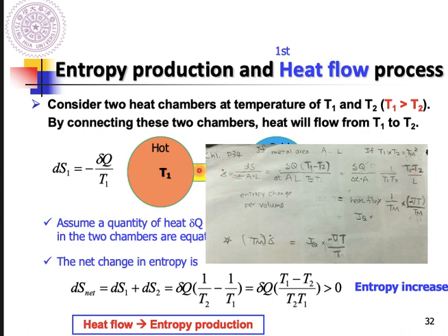Usually, in most cases, the flux goes from here to here. So for the gradient term, we usually use the end point minus the start point. So it will be T2 minus T1 divided by L that is the gradient term. So here I get the minus temperature gradient. Okay, so now we have the flux, and this 1 divided by Tm and the gradient term divided by Tm, right?